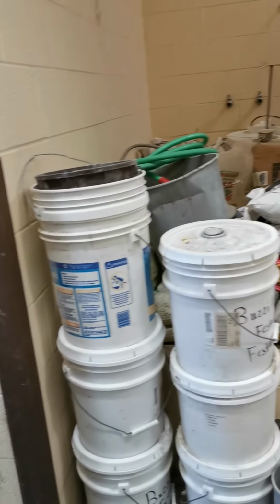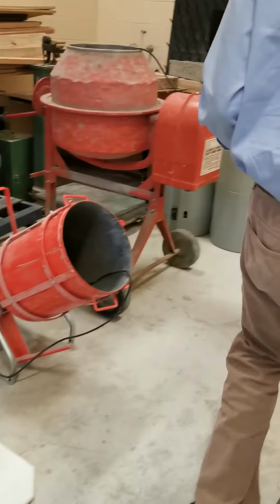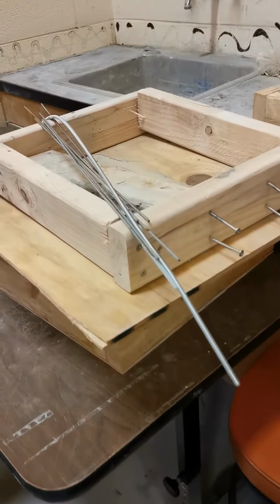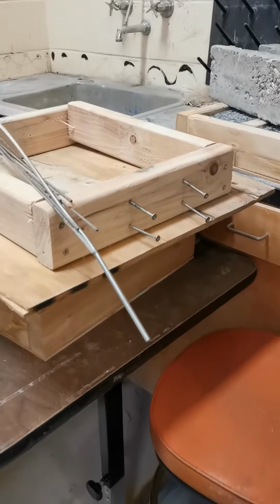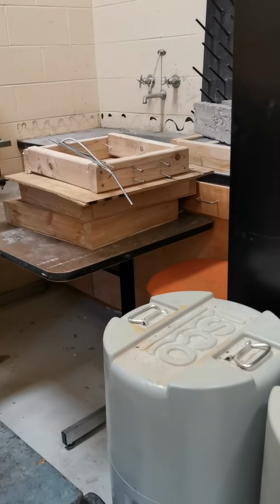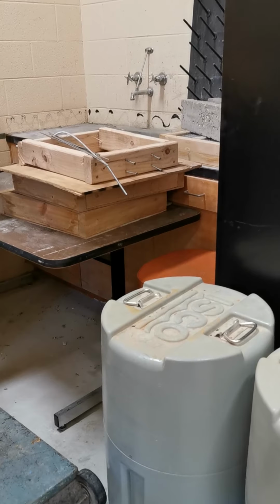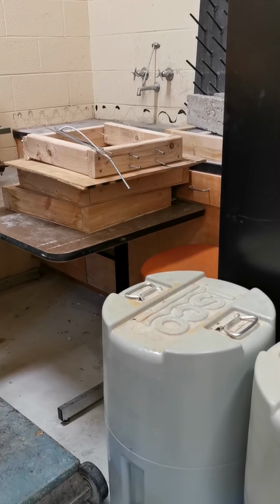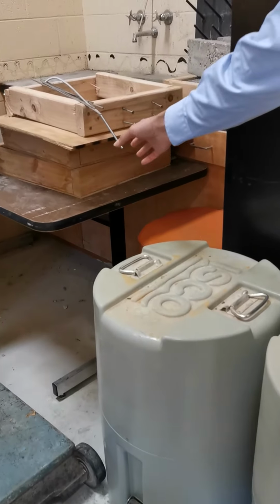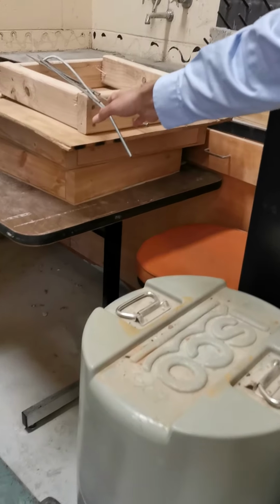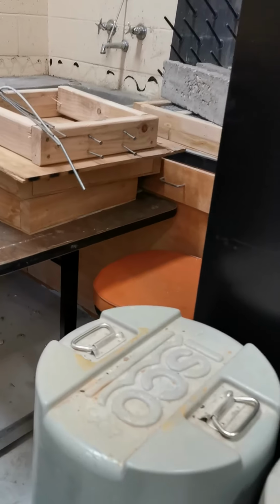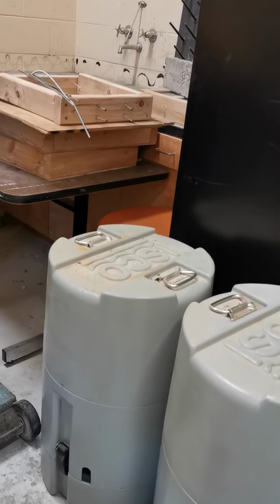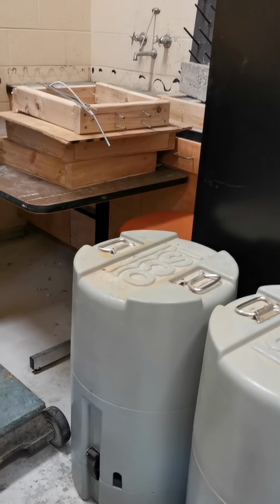So after the mix design, the concrete is poured into wooden molds, and in place of the standard rebars, since the standard rebars are a bit too large for the scale at which we are testing, we are using tie rods. The students use tie rods both for longitudinal reinforcement as well as the shear stirrups, and while doing the calculation, they also calculate the nominal capacity in shear.